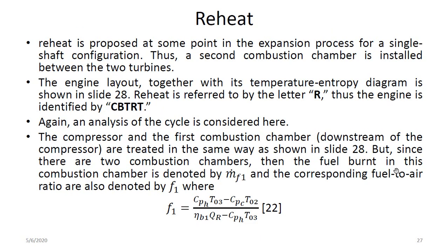Now let's look at reheat. Reheat is proposed at some point in the expansion process for a single shaft configuration. Reheat is similar to installing an afterburner in some turbojet or turbofan engines for aircraft that require a higher takeoff thrust.